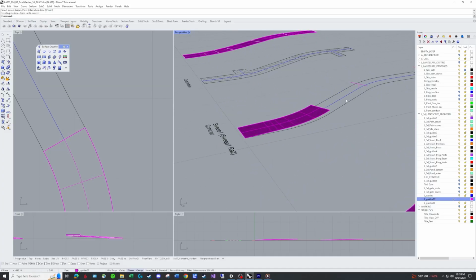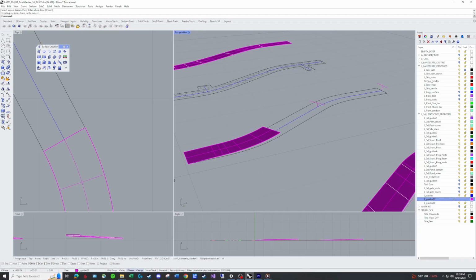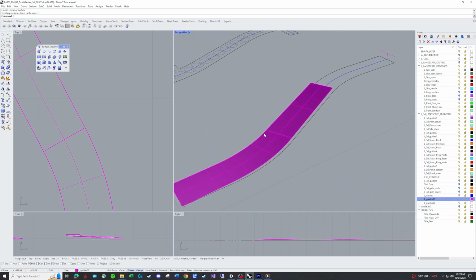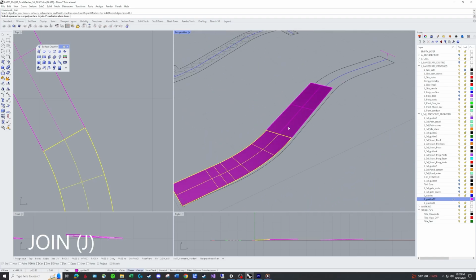And now there's two ways to do this. I could just sweep this all the way through. I've actually done this ahead of time to see what would happen, and sweeping this all the way through is exactly the same as what I'm about to show you. But if you ever get in a situation where, let's pretend this is kind of steep, this is pretty flat, and this is steep again, well, this middle section, maybe you could sweep it separately, or you can just give it the old 4 points surface, and as long as these two align and are precisely together, you can join them.